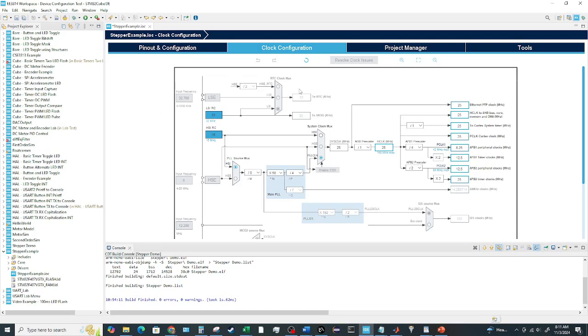Okay, so let's just verify our clock real quick. If you select no on the default peripherals, it should load up this configuration, which is using the internal clock with all these default parameters, and you don't have to worry about this weird clock down here. Everything comes out to about 12.5 megahertz for the APB1 timer, for the lower speed timers, which is what we used in our calculation, right, 12.5 megahertz. Everything looks good there, so I'm going to generate code.